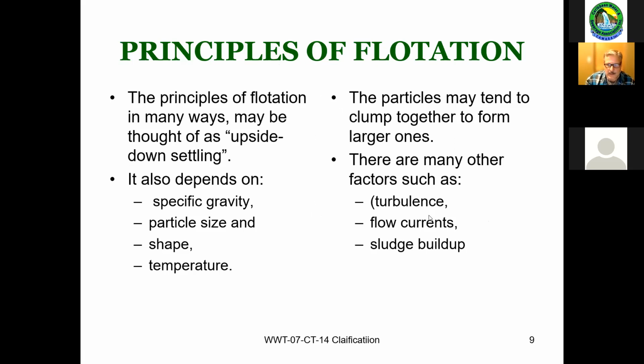We also talked about how primary clarifiers not only settle the sludge out at the bottom, they also want to slow things down enough so scum floats on top. Anything that you can remove in a primary clarifier, or the majority of it, you typically couldn't treat in your bioreactors. If all your scum and sludge went right to the plant without a primary clarifier, you're not going to be able to treat that. It's just going to wind up in your secondary clarifiers or flow right through to your effluent. So that's why you're trying to remove it at the front end.